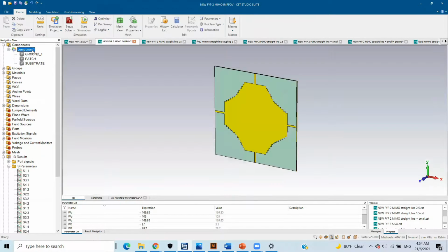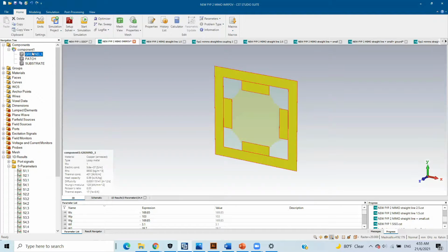As we can see here, our 4-port MIMO design was created by joining 4 patches of the same size from the previous single port design. After some alterations, deleting common areas between the patches, this was the final shape of the patch. Each side of the substrate is connected to a feed line, and each feed line is supported by a ground.